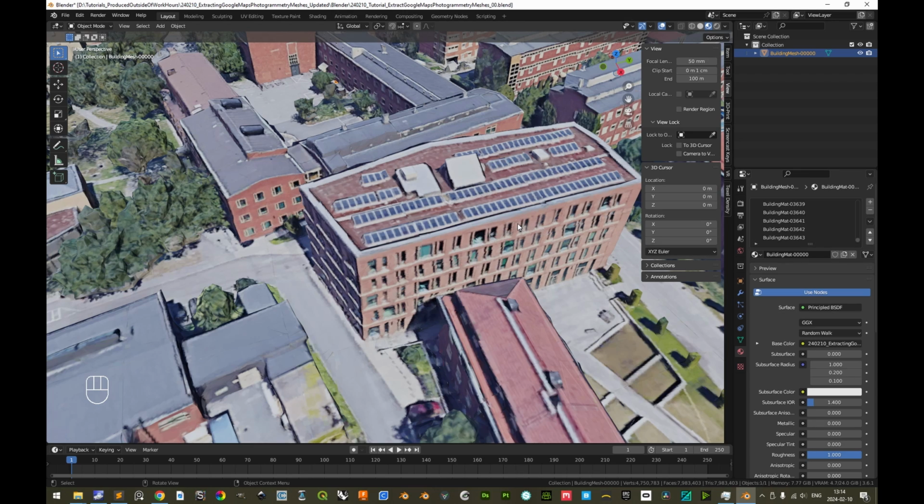That is very inefficient if we want to use it in a separate software such as Rhino or Unreal Engine. So our first priority from here is to create a duplicate of this object, remove all material slots and only use one singular material slot, and then project all of the textures from these 3,644 material slots of the original object onto the one with only a single material slot. We will do that now.